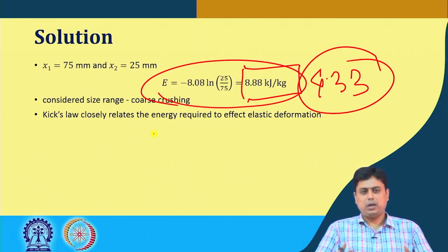Is it for the coarser particles? Is it for the finer particles? What is the ultimate result that you are producing? What is the desired product size, and from where is it happening? If you see there are chances of huge surface area creation, then the energy required would be more reliable from the Rittinger's prediction.